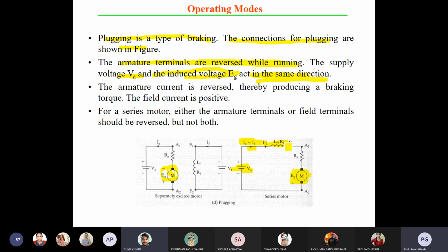Now you know that armature windings are grooved inside your armature. The armature winding is rotating inside the magnetic field, and due to that rotation there is cutting of flux, and cutting of flux means dphi/dt, which causes induced EMF. So the cause is the armature current, and the effect is your induced EMF. The cause definitely counters the effect. That's why the back EMF polarity is always reverse to the polarity of your armature current.